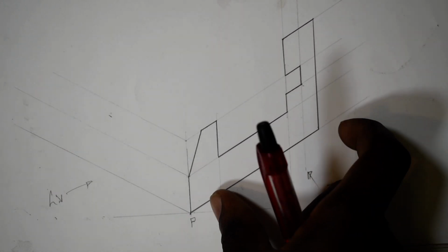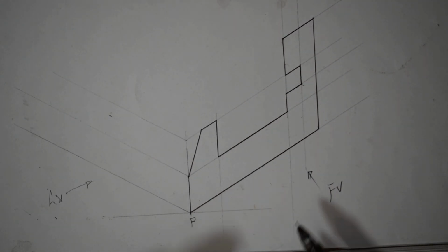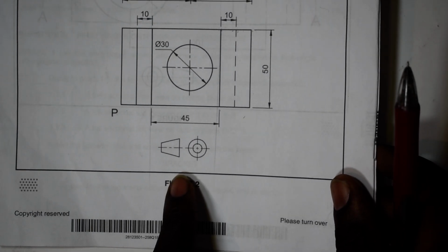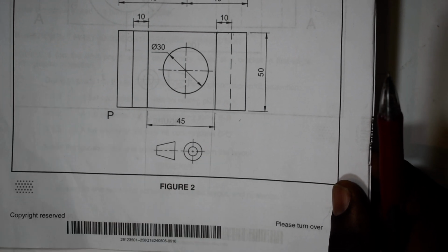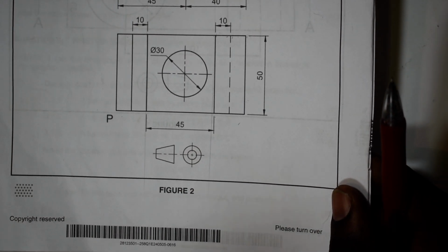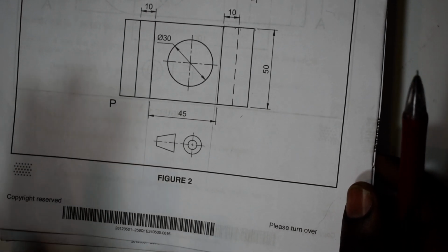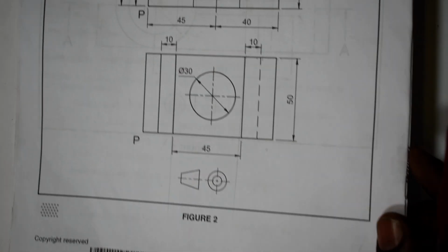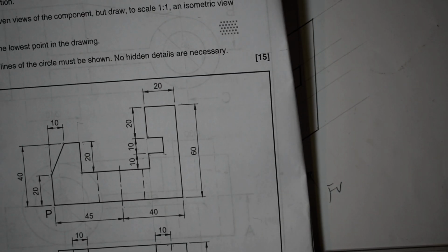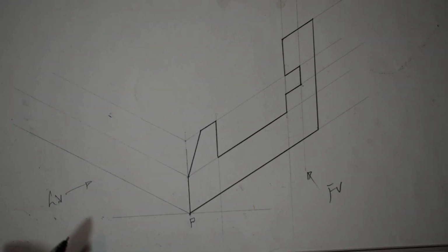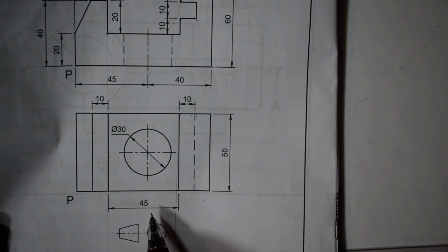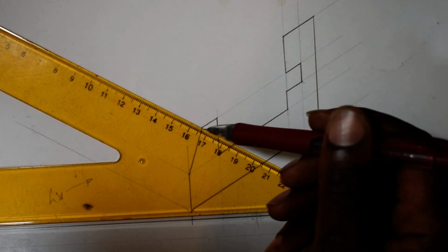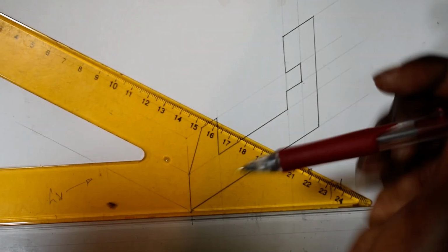So if you draw this one this side, which means you didn't follow the projection symbol. Of course, at the end of the day, we are going to have the same thing but in a different direction. So we don't create our own question. Be careful of that. Follow the question. So we are going to have a left view this side, which is what is omitted. You understand? So now I'll take all the points at an angle of 30 degrees clockwise direction.